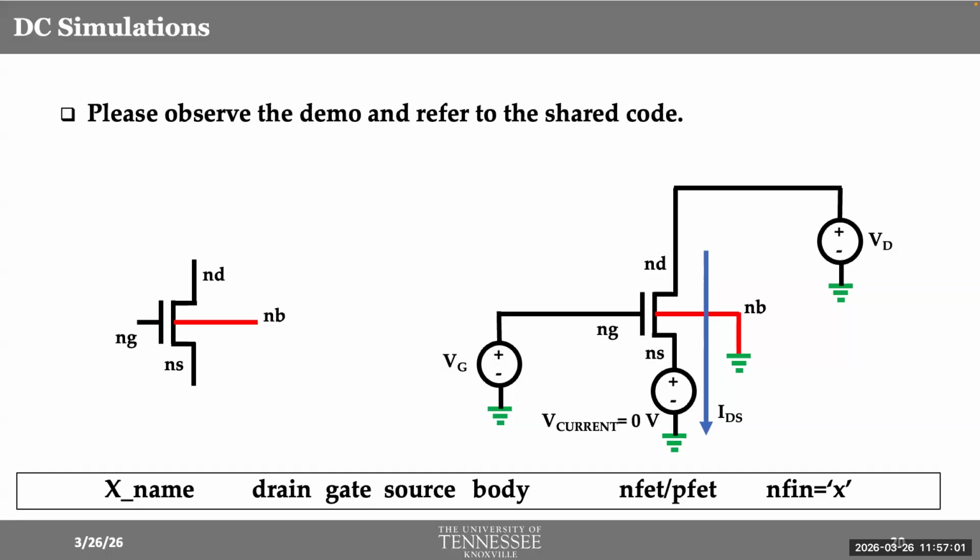That's an option, but typically I don't connect any other resistor here in this circuit. So the only thing that I can connect is a 0-volt voltage source, which doesn't change anything. It is just there. But the way SPICE is coded, it allows you to see the current of a voltage source flowing through that voltage source. So when I connect a 0-volt voltage source, it's as if there is nothing there. But I can then use this voltage source to see the current through that line. And notice that current through that voltage source is essentially the drain current, don't you think? Drain current. So right here.